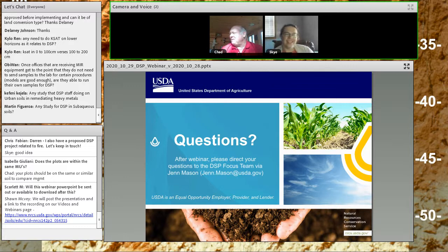Someone's taken to IM for questions. Do you think, Chad, that you have any advice for KSAT? For DSPs, I'm very interested in what's happening at the surface, but I think we do want to know more information about lower depths, especially if you're taking a characterization pit. We really want as much information on those as we can get. Remember, if you're using, for instance, the meter, you need a 15-centimeter head for that, so you're going to have to maybe combine, and it'll be more layers than horizons per se. You'll just have to use best professional judgment to get that data.